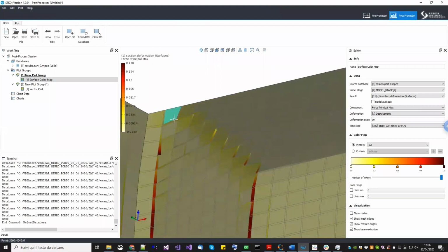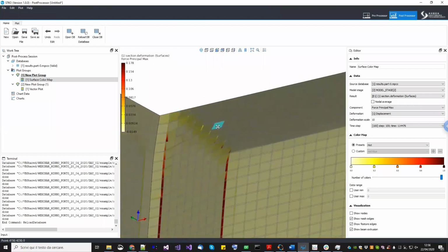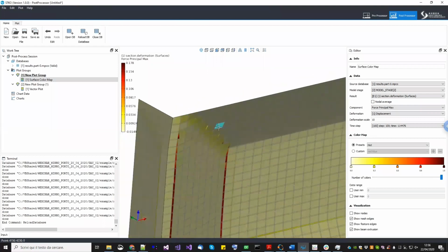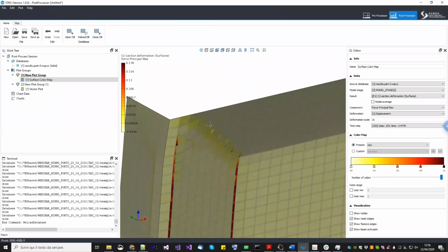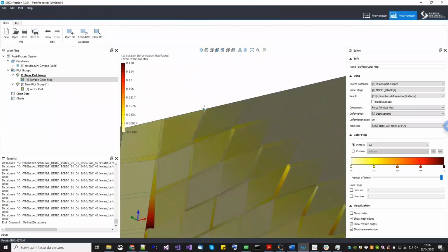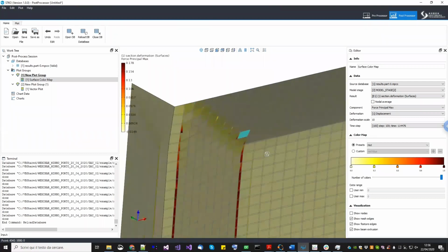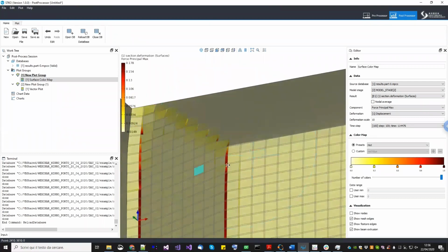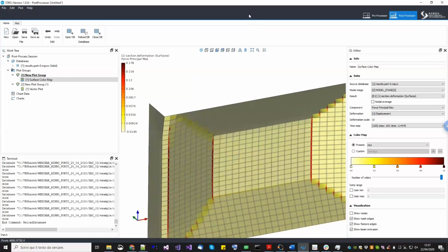This is due to the fact that the two materials are completely different, and that, of course, there is strain softening. So the entire strain gradients are trapped into the mortar joints. The mortar joint instead has a typical dimension of 10, which is less than the thickness. That's why in this case, the thin plate theory does not apply.